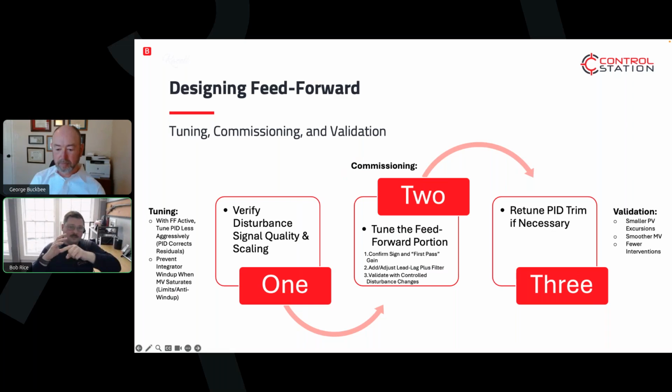And it's going to be in thousands of gallons per hour, for example. And so I'm controlling the level by adjusting the feed water flow. The steam demand is the feed forward variable. I've got some sort of steam demand that's pulling out 1,000 pounds per hour of steam. Well, that's a pretty easy math balance. If I'm drawing out 1,000 pounds per hour of steam, guess how much feed water I need to put in there? 1,000 pounds per hour of water.